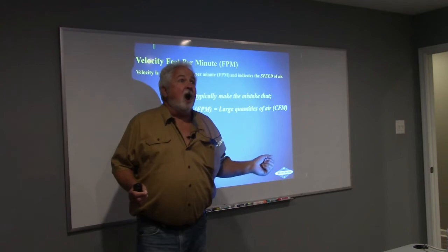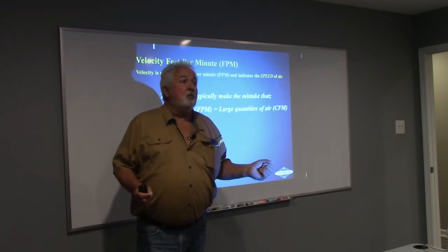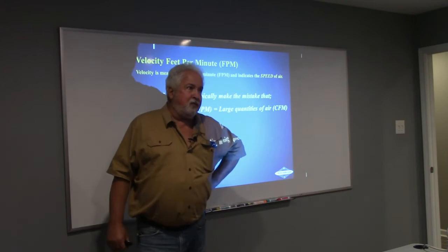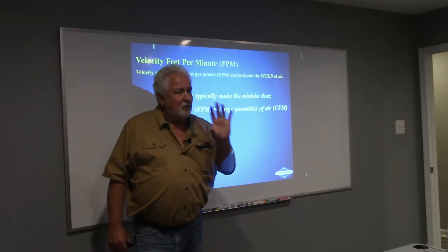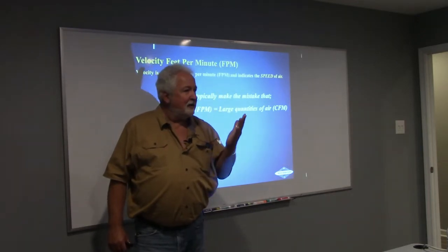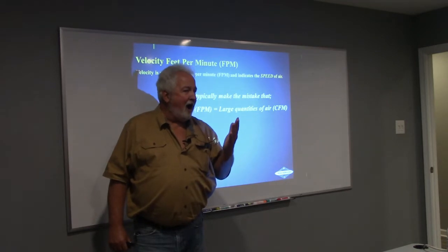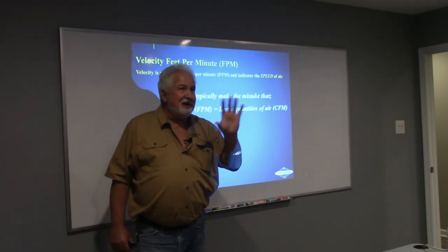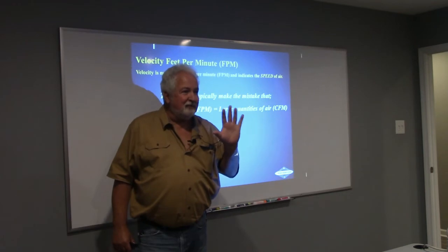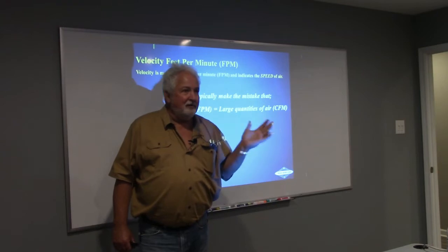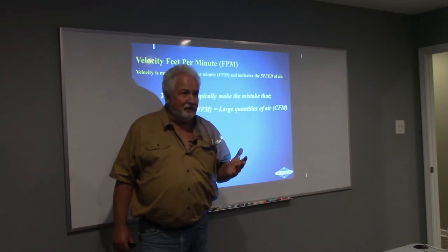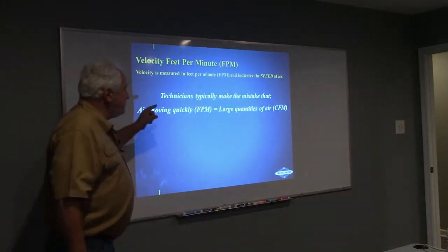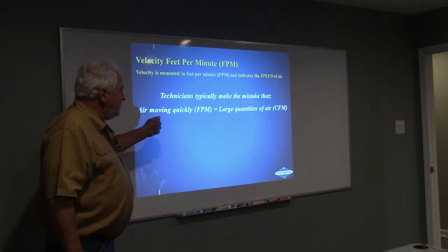Watch. You see what I'm saying? Which one are you feeling with your hand? You feeling it? So you're not feeling the quantity of air, you're feeling the velocity, is that right? All you're feeling is the air moving fast, but you have no idea how much air is coming out. Does that follow? You follow me on that? Okay, cool. So technicians typically make the mistake that air moving quickly is large CFM.